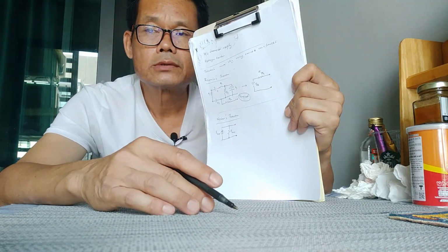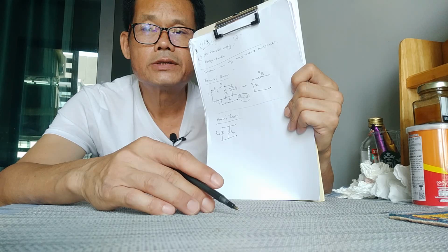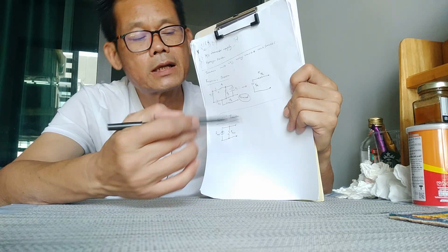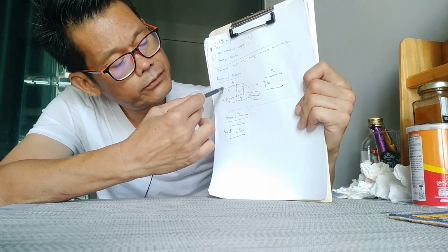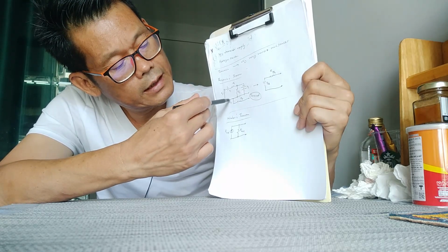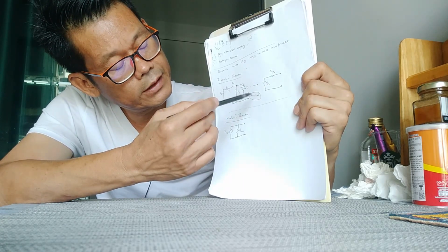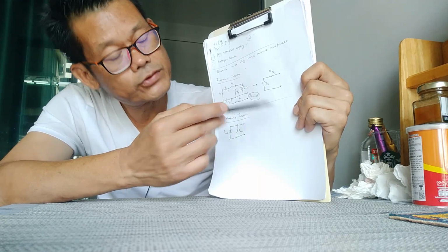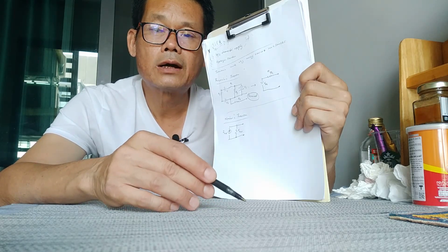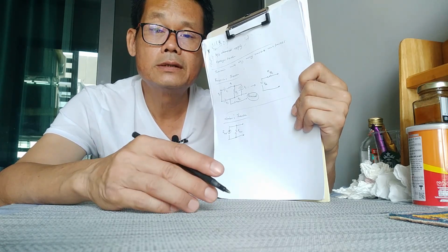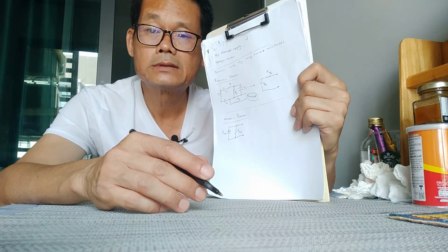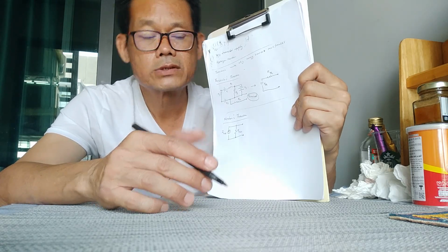What about RTH? Well, for RTH, you can short the voltage source, and then you need to apply Ohm's law: V equals IR, so R equals V over I. You already have V equal to VTH, and I is going to be the short-circuit current. What does short circuit mean?